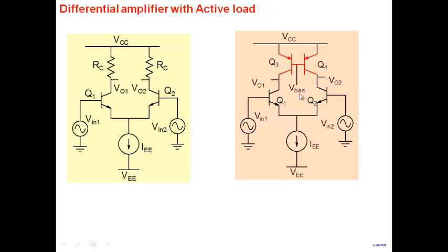So a little bit of error here may cause 2 milliamperes to flow instead of 1 milliampere. If you don't put the value of V bias properly, this will try to conduct 2, and this one is trying to make it conduct 1, and you get into a problem.